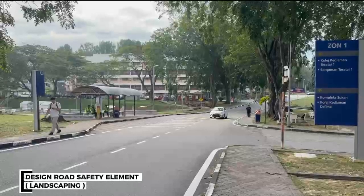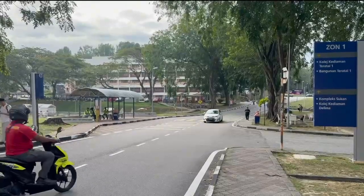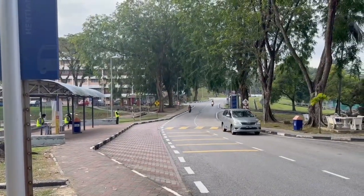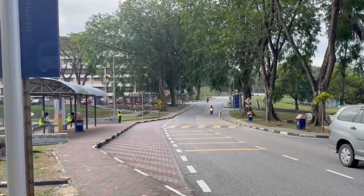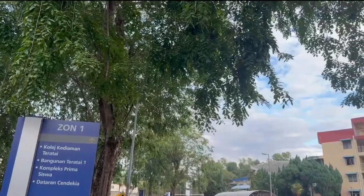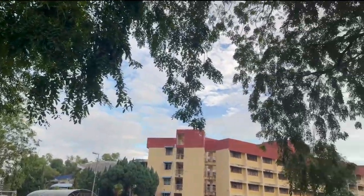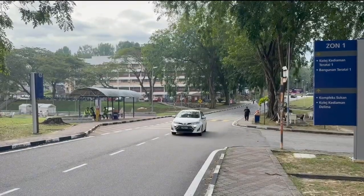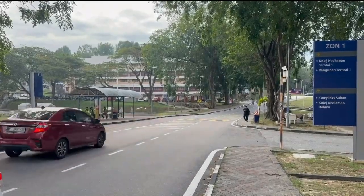During our observation, we found that trees are planted too close to the road with excessive branches extending towards the carriageway, which not only may pose a safety risk if branches fall onto the road and obstruct passing vehicles, but also significantly reduce the required clear distance and restrict the line of sight for drivers. This limitation can endanger road users, particularly motorcycles and vehicles traveling at high speeds, as it reduces reaction time and increases the likelihood of collision, especially in areas with limited lighting and adverse weather conditions.